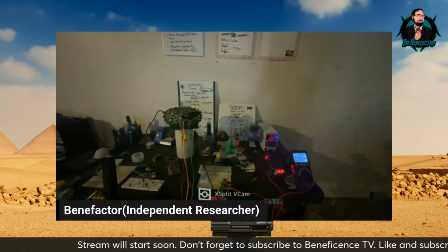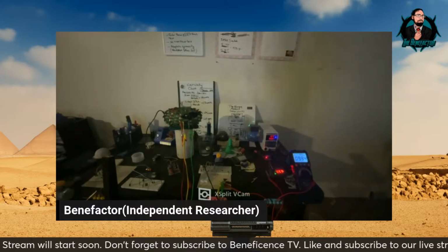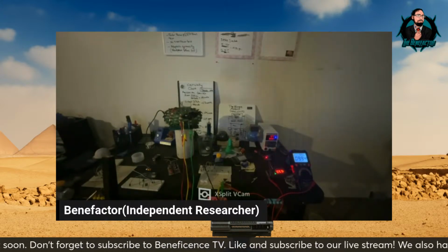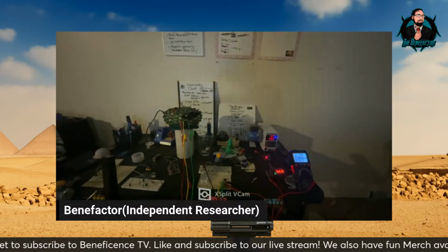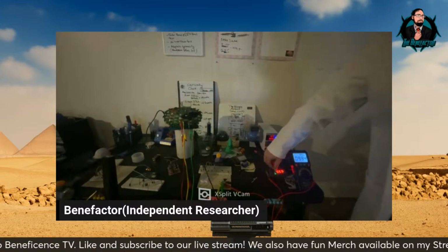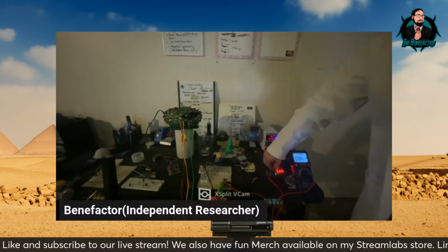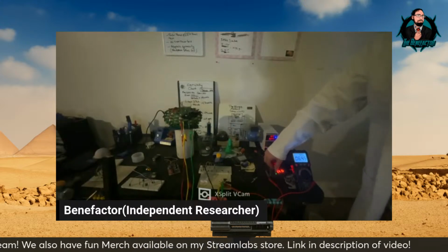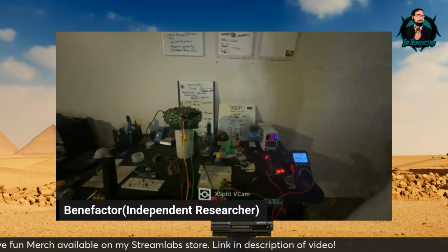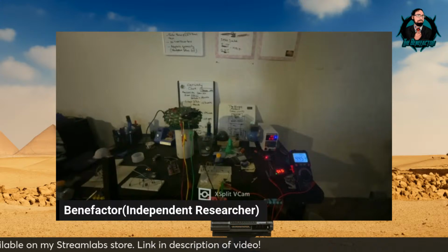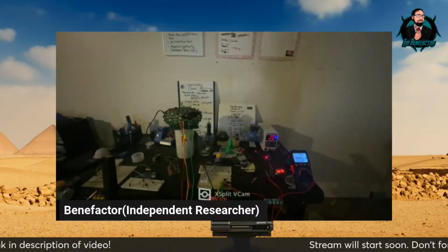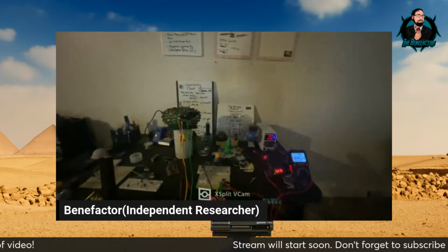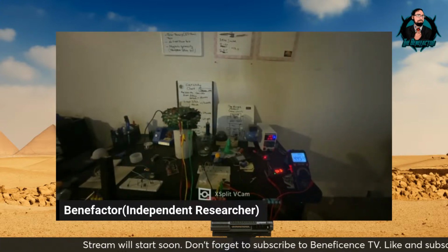So where are you at on your duty cycle? 30%. Bring it down to 10%. So now you're trying to get the PWM going, to get that thing to jump a little bit. Maybe we can get it to jump. Who knows? Nathan might be onto something there. Try down to 5 volts and turn the duty cycle to 100. If we can get it to do anything, it's going to be like Nathan said.